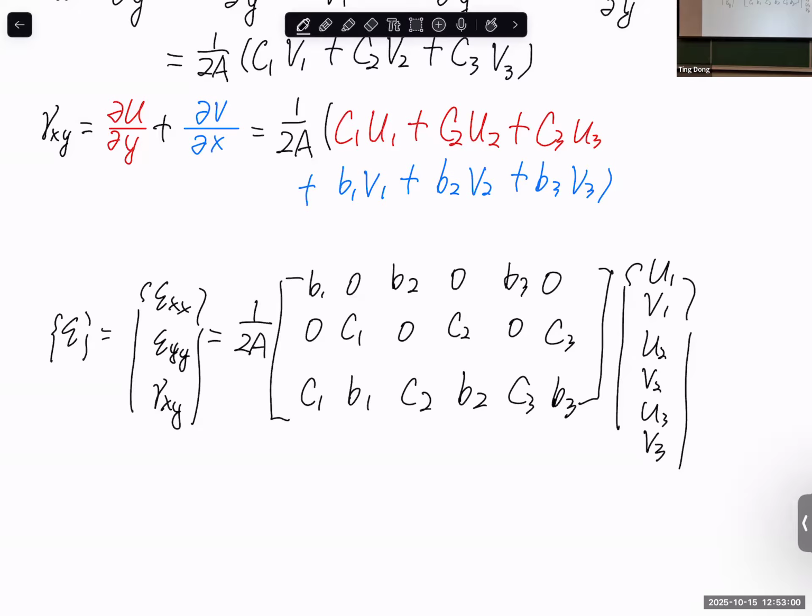Oh, remove the center node. Yeah, so remove the center node. You need to watch tutorial 2. The whole second tutorial is about how to modify the input file. So when you create that shape with the cross part, by default Abaqus will automatically generate a center node. And when you run the job successfully, of course, it will generate an input file with the center node in the input file.